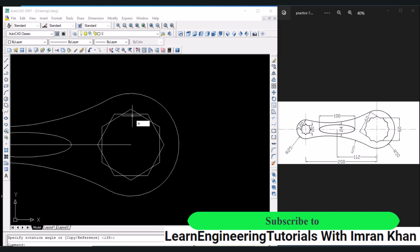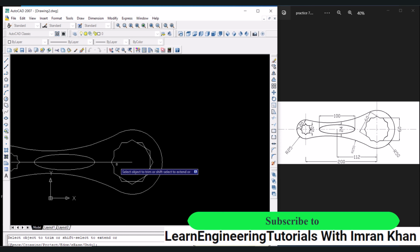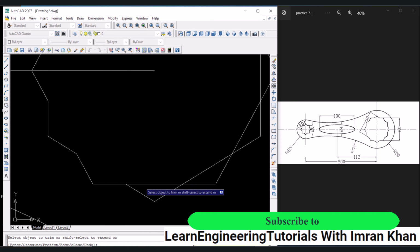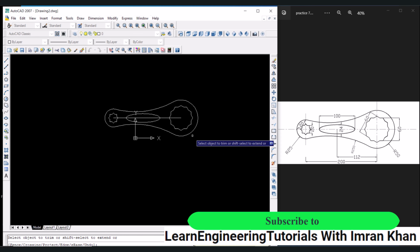Now perform trimming, so TR, enter, click, the object is complete. We have to extend and add the center line, so for that click on this line,